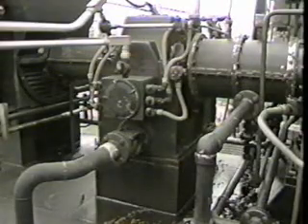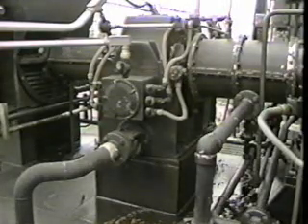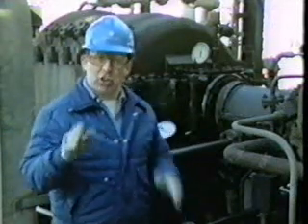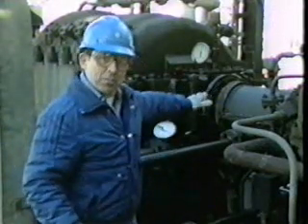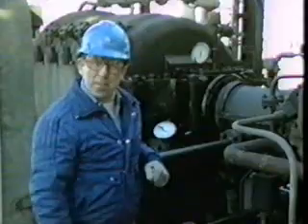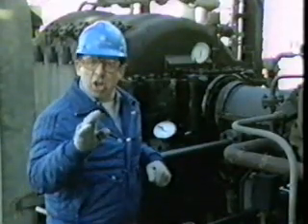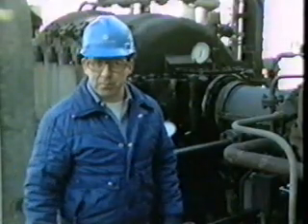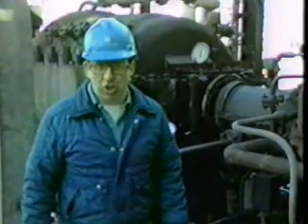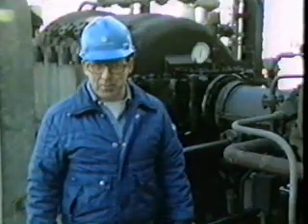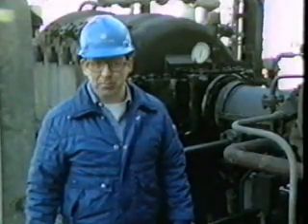Gearboxes can either be an integral part of compressor construction, or they can be external auxiliary equipment connected between the driver and the compressor. Almost all compressor driver applications use some sort of coupling. Couplings are used to transmit motion between two shafts that are almost but not quite in perfect alignment. They must also be able to withstand changes in compressor load or stoppage of the driver altogether. Now, there are two types of couplings commonly used to connect the driver to the centrifugal compressor: the gear coupling and the flexible diaphragm coupling.